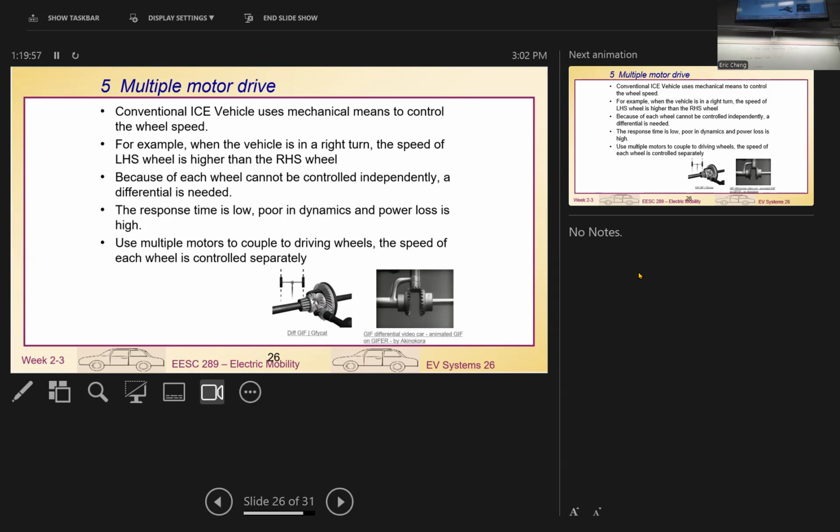You see, anti-lock means under skidding, maybe on a slippery oil surface, we need to control the brake, changing it at high frequency braking, 20 hertz on, off, to eliminate the skidding. That is to say we usually use a hydraulic pump system to control that ABS. That will be a disaster.